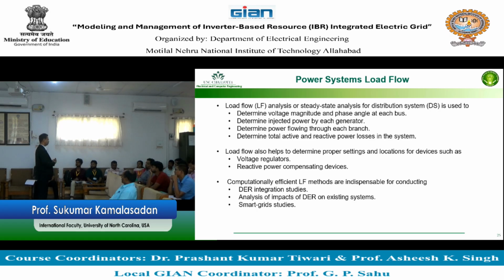So planning purpose means what? You do the load flow again when the load is changing in the future. Yes, you can do the load flow multiple times as a tool to understand what the voltage magnitude is. So what we call the state variables for a load flow: when you run a load flow, it is to know the voltage and the angle of the voltage. State variables in the load flow are basically voltage and voltage angle.